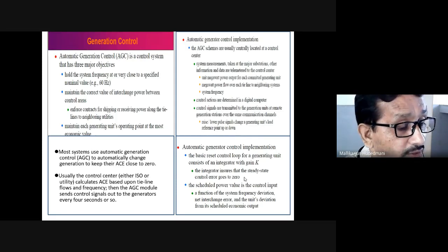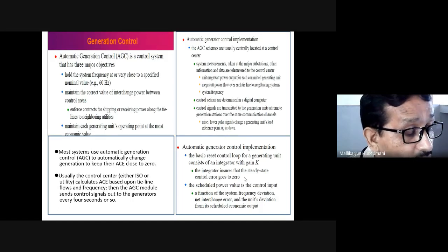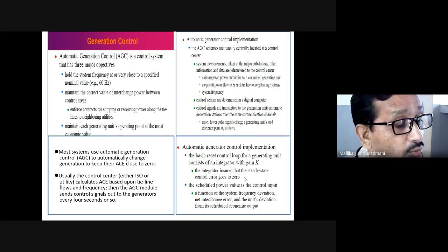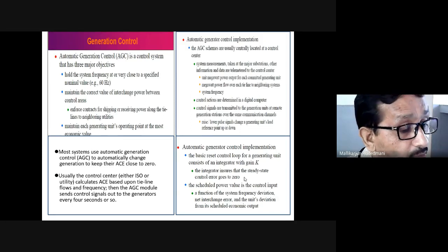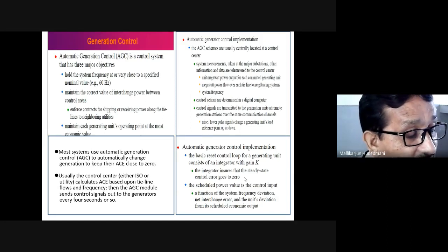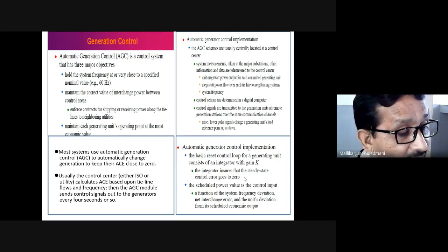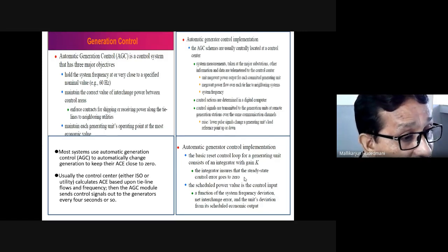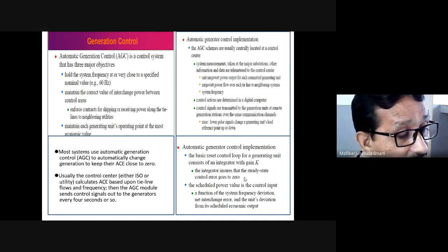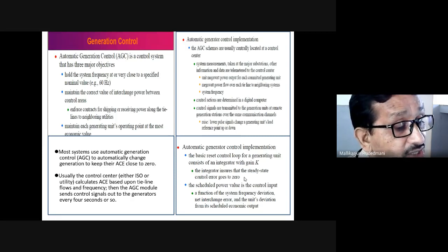So, automatic voltage regulation and automatic load frequency control are the two other control loops to be implemented around the generator, which will have PI, proportional integral, or PID, proportional integral and derivative controllers, which in turn try to minimize the error and overshoot and keep the stability of the control action as the generator changes.